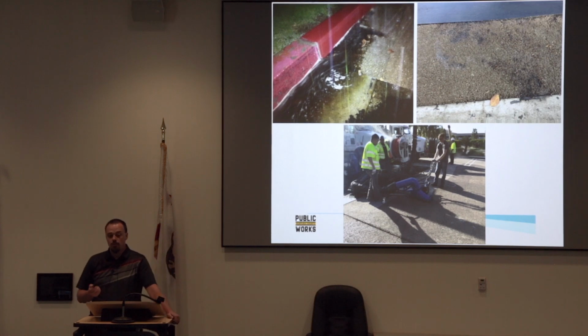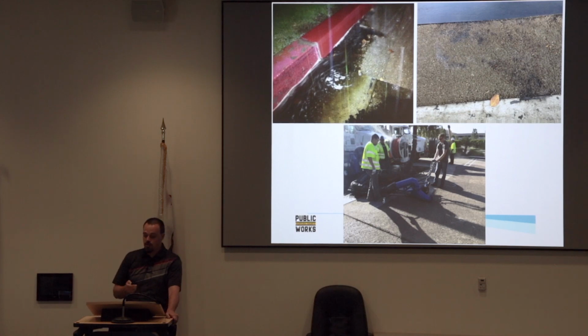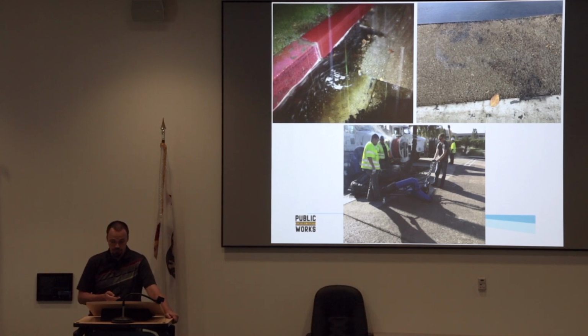So we do pre-infiltration testing as well as post-infiltration testing of the surface to see how efficient this is. Initially we budgeted to do these cleanings about 3 times a year if needed, but we found that doing it twice a year is sufficient. So we usually do it once before the rainy season and then once again after a major rain event is what we'd like to do.